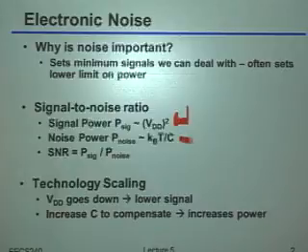As we'll see very shortly, maybe not this lecture but certainly by next lecture, the total noise you have at the output of that amplifier is almost always set by kBT divided by C, where kB is Boltzmann's constant, T is the temperature of your circuit, and C is the total capacitance at the output of your circuit. Notice there's not much you can change in that expression.